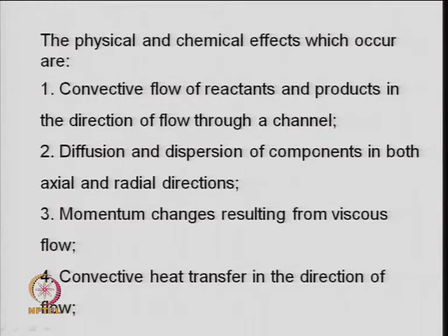I am not going to talk about the design of this kind of reactor, but very quickly, the steps in terms of transport properties are these. You have a convective flow of reactant because of the velocity term, C times V, so convective flow of reactants and products in the direction of flow through the channel. Then second is the diffusion and dispersion of components in axial and radial directions.